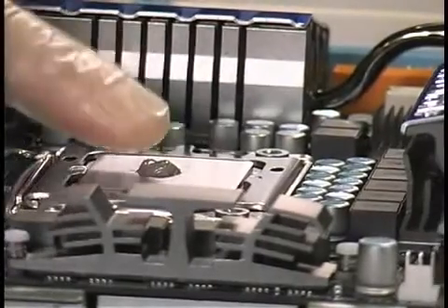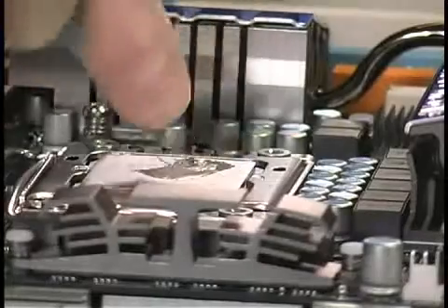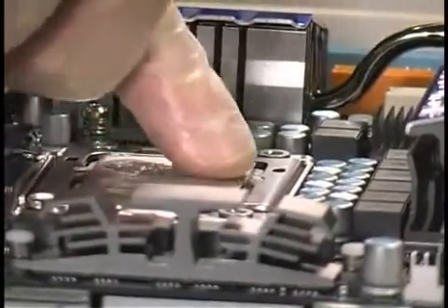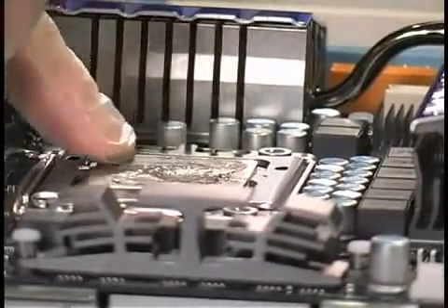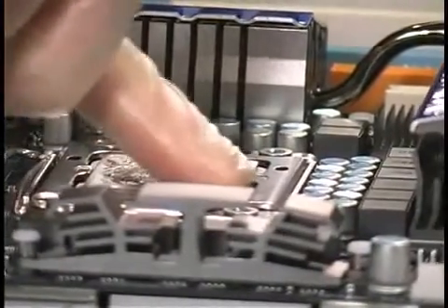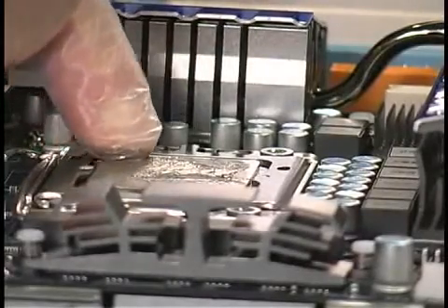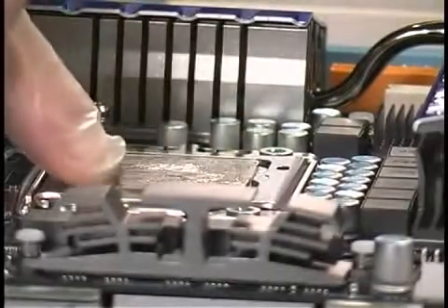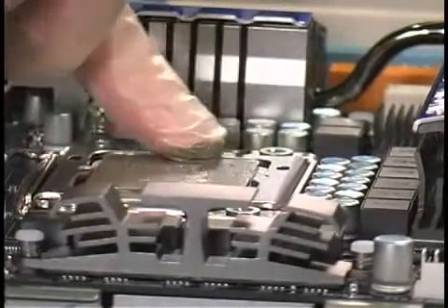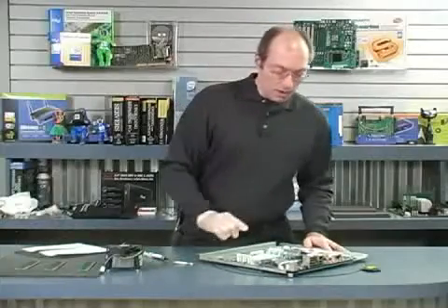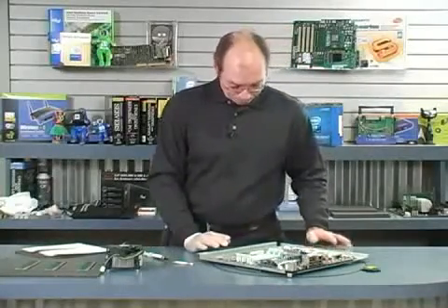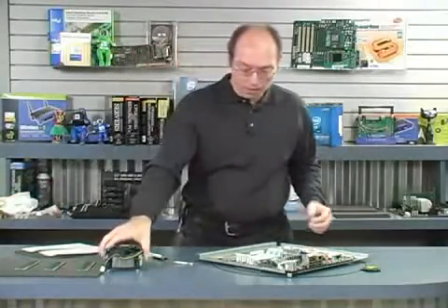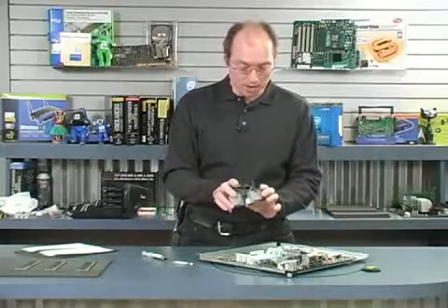Okay, now, once that's there, you want to use the glove and basically smooth it out to where it covers most of the top of this heat spreader. Now, even if you don't get the entire heat spreader covered completely, it will ooze around, especially as the force of the heatsink is applied on top of it. So, okay. As you can see, I've got this stuff pretty well smeared over the top of the heat spreader. Now I can take the glove off. Don't need that anymore. And we can actually install the heatsink on top of the processor.